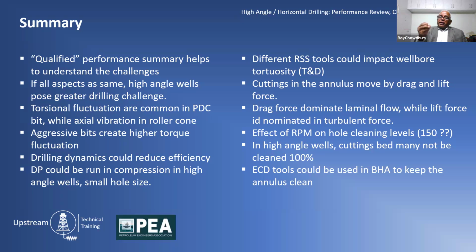The cutters towards the gauge are doing the biggest circle, so their work rate is much higher than those in the center. So you need to be extremely cautious about what you use for drilling. Where is the cutter placed? Based on the placement of the cutter, you decide whether to go wear resistant or impact resistant.